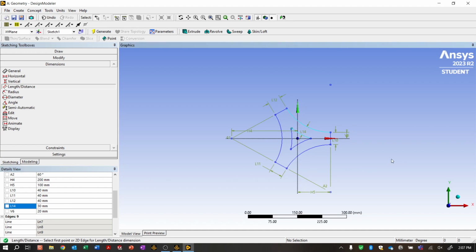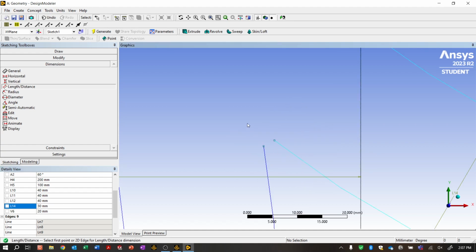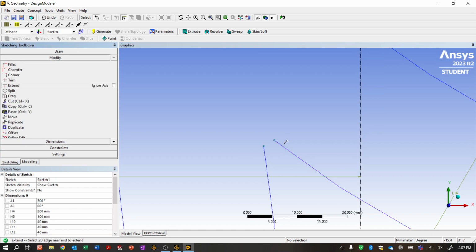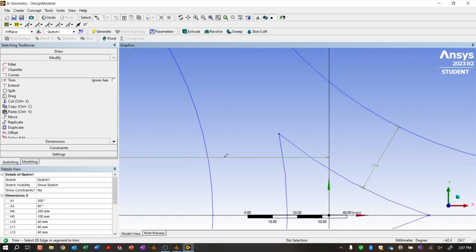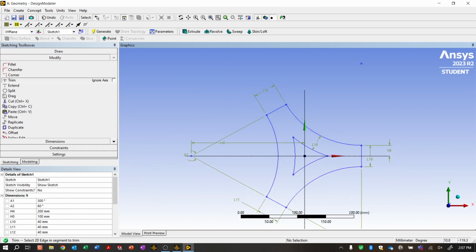And those all grew the same amount, and these two ends that still stay connected, it did not. So I may need to extend those. And this guy. And now I can go back and trim this line off. There we go. So there's my bit. I need to do a radii, fillet on those. So I'm going to do 10 and just fillet that corner, this corner, and that corner. Now it looks like those radii are not fully defined, but again, that's fine.